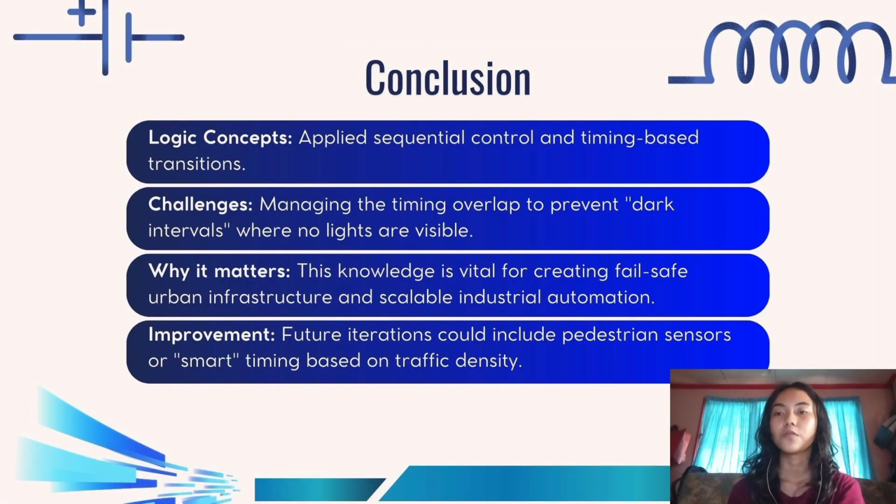In this project, we were able to apply important PLC logic concepts, especially sequential control and timing-based transitions. One of the main challenges we faced was managing the timing overlap. We had to make sure there were no dark intervals or moments when no traffic lights were active. Solving this required careful timer coordination.